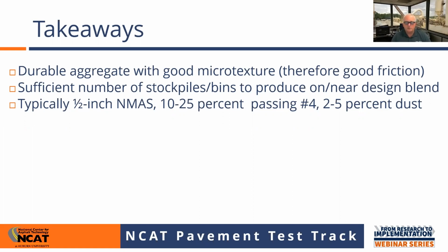So if you're someone who puts these designs together, look at the history that you have with the aggregates, and if you know you're going to have some breakdown, don't design on the fine side of that range. Try to stay in a place where you're going to be able to produce in a really healthy spot in terms of what that stone skeleton looks like. Same thing's true with the dust. If you have less durable aggregate, you're going to end up with more dust, and that's going to close the mix up.